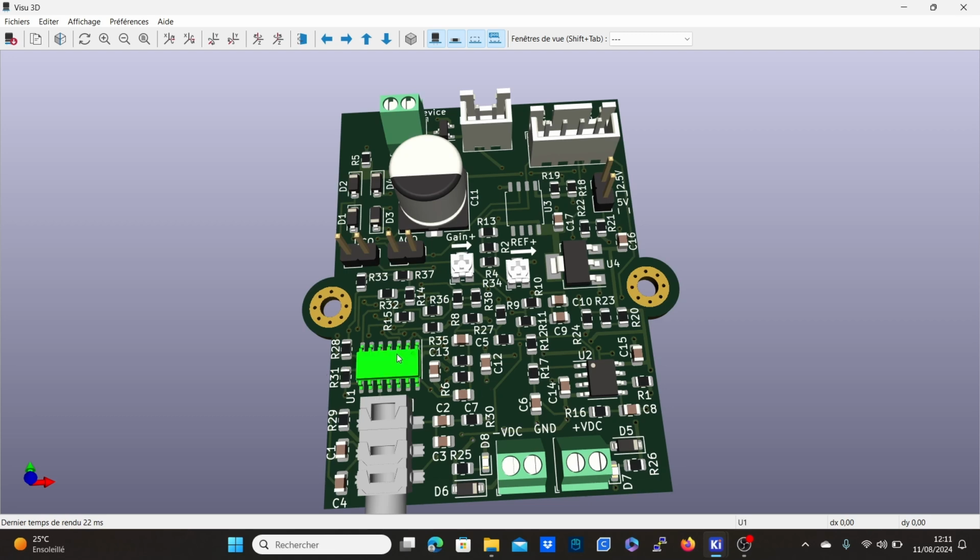So you always have that. Or if you have some special components like, I don't know, your instrumentation amplifier or your comparators, these kinds of things, make sure that the components are available first before designing the PCB, and it will really make your life so much easier, because you may end up in a situation where you have to reroute everything all over again, and that's not a very pleasant experience.